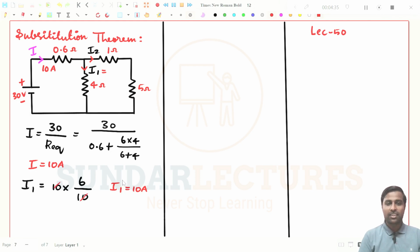If you cancel this two, it will be 6 amperes, right? Maybe I have written it wrongly. So this will be 6 amperes. I have written here 6 amperes. And if it is 6 amperes, then obviously 10 amperes is coming in, 6 amperes will go here, and it will be 4 amperes. Maybe we apply KCL at this point, I1 is coming in, 10 amperes is coming in, 6 amperes is going away, and 4 amperes should go away. So I2 should be equal to 4 amperes.